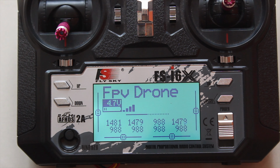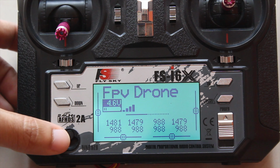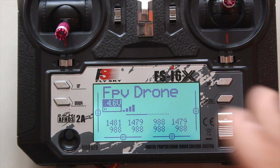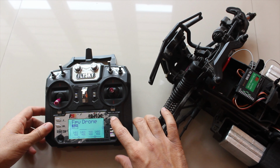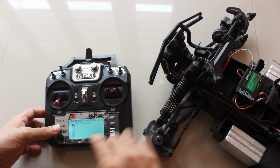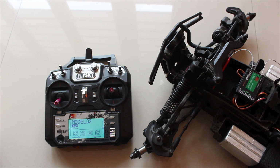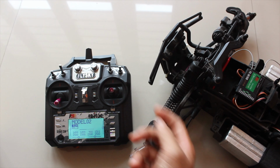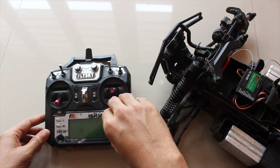So now I can test the quad and see how it responds. But before I do that, let me quickly set up another model using my RC car so that we can very briefly go through all the steps that we just covered. I'll go to the model settings and create a new model. Whenever you create a new model, if you want to bind the receiver, you'll first have to turn off your radio transmitter and then turn it on.